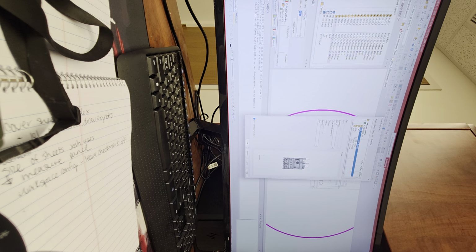Anyways, each one of these items, you have the option to rename this description as to what you call these contact points. So instead of just calling it aux-f, a very general term, very general statement, could be anything, you can call it out to be something very specific. You can use these description fields to say this is my starter, and then maybe starter 1, starter 2, starter 3 position, etc. So you can manually type in anything you want, because this description reference only matters to you. Because you want to go to the other component that receives it and say, go and connect yourself to this name that you're specifying right here.